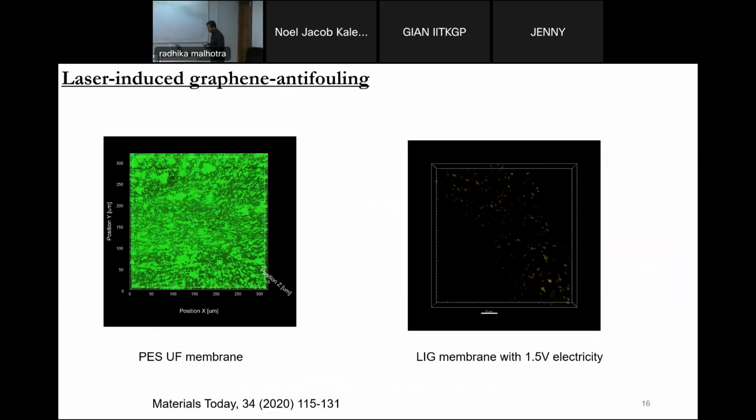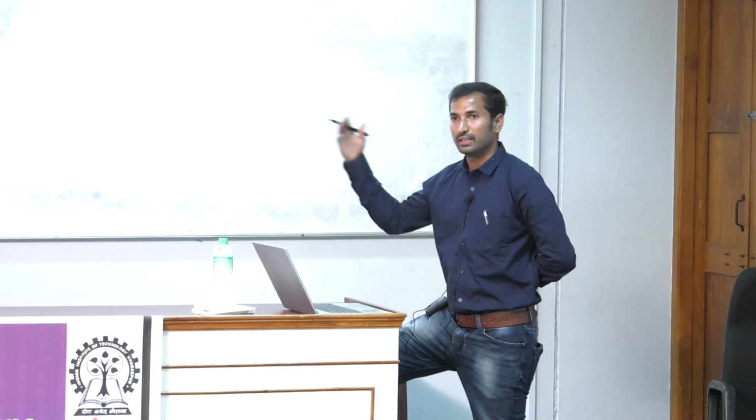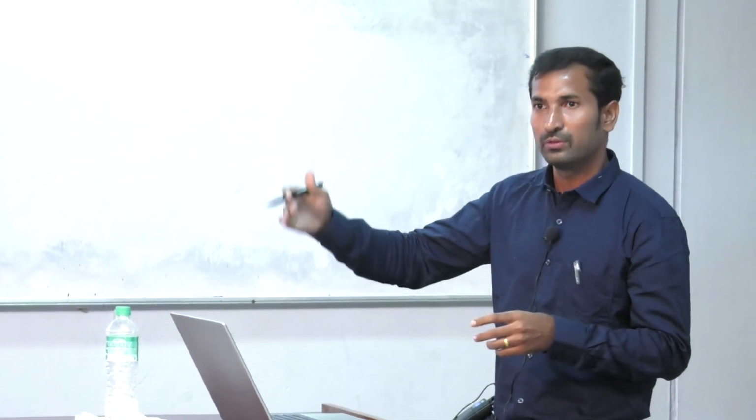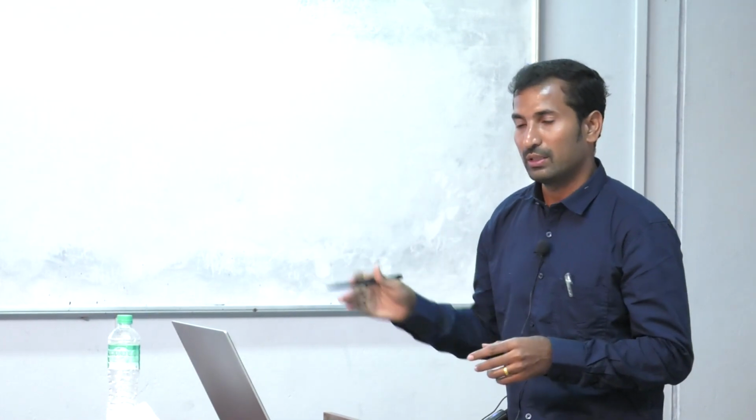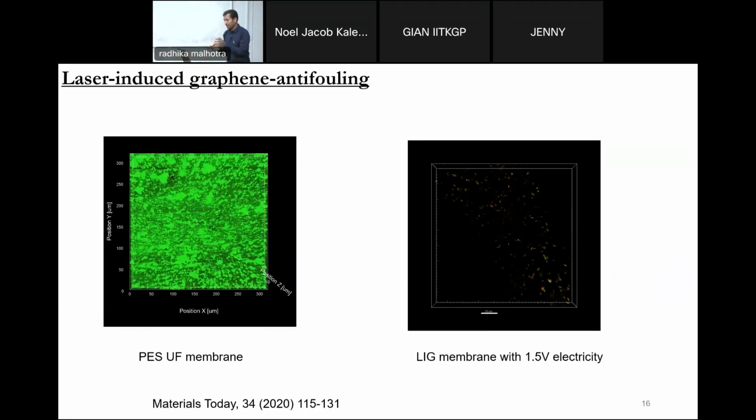Here I show you some of my research examples. We have studied this especially for biofouling prevention experiments. We ran for 3 days using model bacteria. By continuously supplying nutrients, the carbon source LB, we gave food for the bacterial growth. We estimated that the bacteria can grow within 72 hours, which mimics about 6 to 8 months of the real experiments. That's what we calculated.